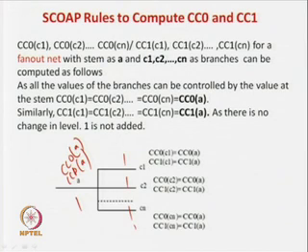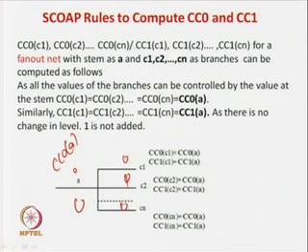So, if we know that CC 0 of A is some value, then this 0 is applied and all the nets will be 0. So, if we know the difficulty of controlling A to 0, then automatically the same value will apply for CC 0 of C1, CC 0 of C2, CC 0 of C. Everything will be the same, because if you just apply 0, it is automatically carried over, and there is no level shift because there is no gate, so you need not add a 1.